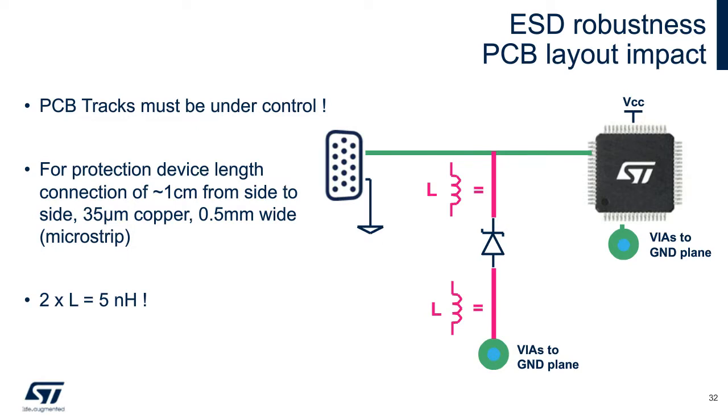High current and the trace impedance cause unwanted overvoltage at the protected IC pins. Depending on the PCB technology, a PCB track impedance of around 1 nanohenry per millimeter of length is introduced. This problem is specifically important for the PCB track parts colored in red in our figure. Let's consider for the next exercise that the single PCB track inductance L is 5 nanohenry.